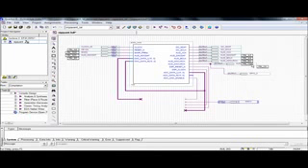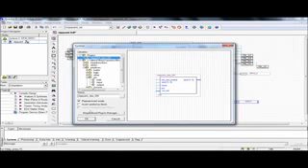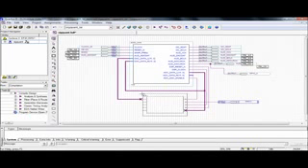We will use this switch to select the output signals from the two quantization settings. Click Symbol Tool again and select the Quantization HDL module exported from Simulink design. Compile the project and then program the FPGA. Set up the audio playback, trigger the switch SW1 and listen to the audio playback. The quantization effect is similar to noise found in the signal.